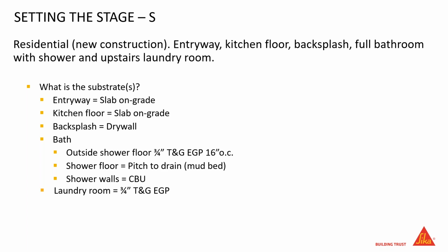The bathroom, outside the shower, it's an upstairs bathroom, so we can kind of tell that by what's going to be on that substrate. Outside the shower, the toilet area and cabinet area is 3/4 inch tongue and groove exterior grade plywood, 16 on center. Shower floor, it's a pitch to drain, so more than likely we're going to be doing a mud bed. Shower walls are going to be CBU, cement backer units.